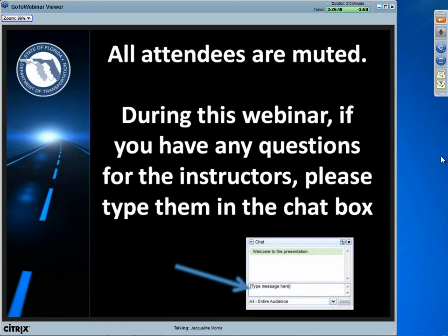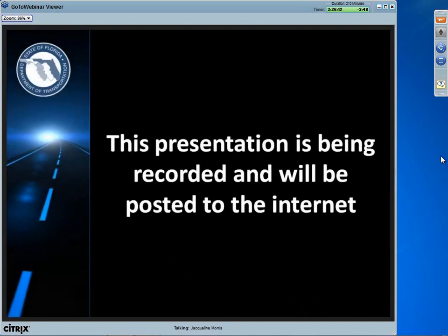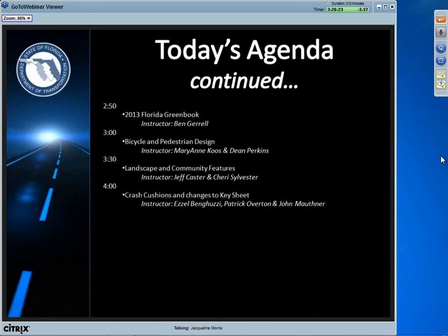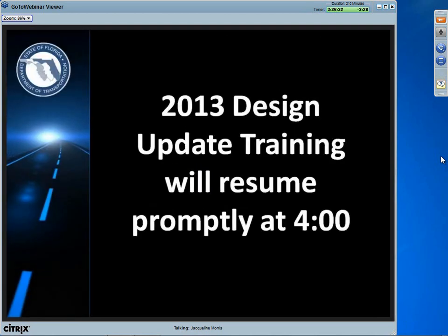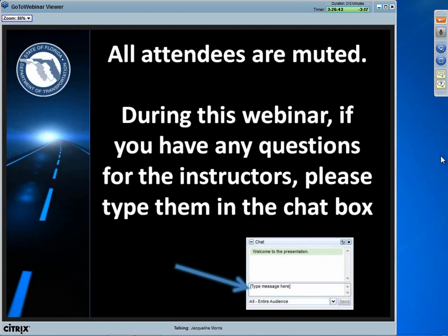But if you are thoughtful, and if you want to build the connection, like here in Tallahassee, we have a short section of our Goose Pond Trail. It tees into Hermitage Boulevard, which has curb and gutter with bike lanes. And there is, at this point, no transition between the termination of the shared use path and the bike lane. So if you can provide this transition in a way that's elegant and doesn't send people out into traffic unexpectedly, I think that would be a laudable goal. But maybe call us and show us what you're thinking of.